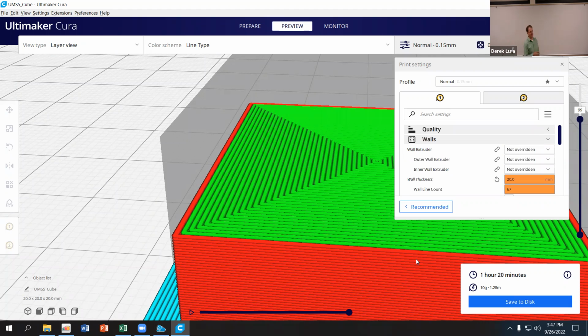What I would recommend that you do is balance the material strength that you need with the number of walls, and then interior support with the amount of infill. So if you have a big volume that just needs to be supported on the inside, use infill. If you need a strong part, use walls, because the walls are going to follow the contours of the part. And so they're going to be able to better distribute the forces for a generic loading condition where the loading is in a direction that you don't know.